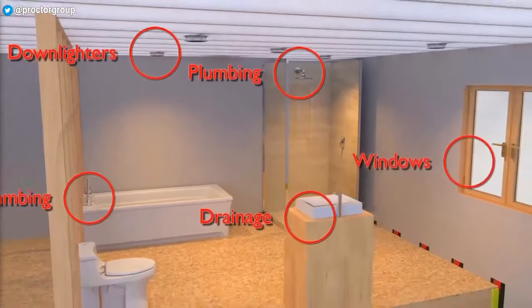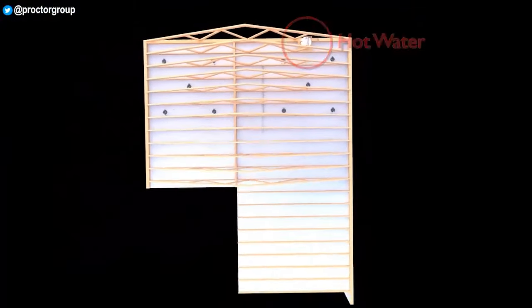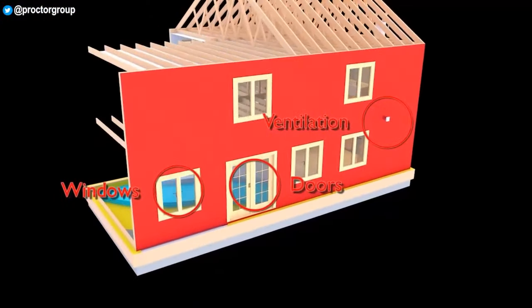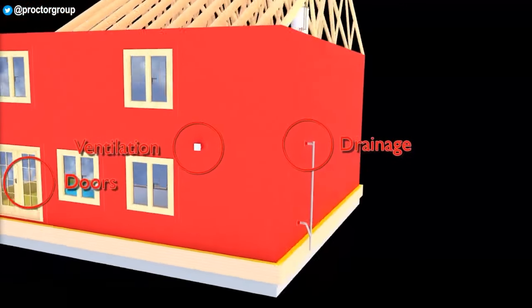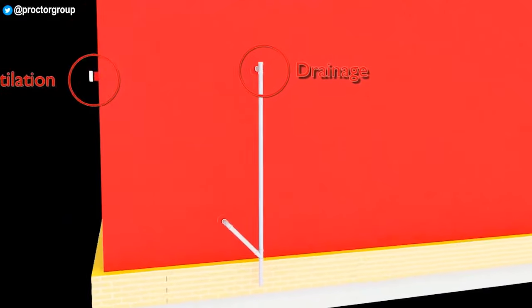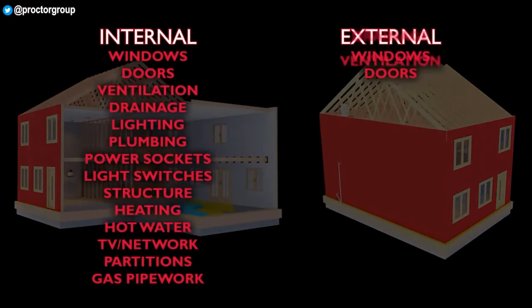Failure to meet the design air leakage rates can have a major effect on the energy performance of the building. Moving the air barrier externally hugely reduces the amount of sealing required, increasing the likelihood that air leakage targets will be met. This in turn allows the use of more ambitious air leakage rates at the design stage, giving significantly improved design flexibility in other areas such as thermal insulation.